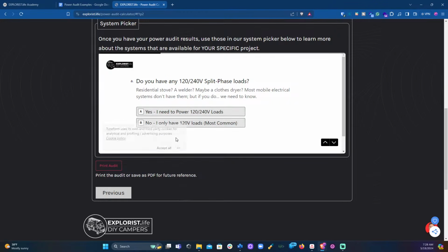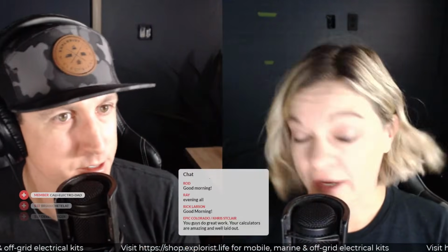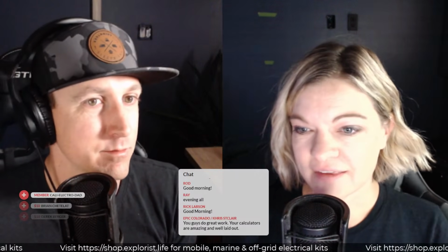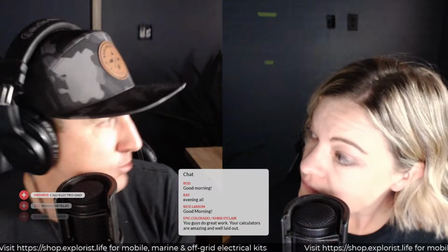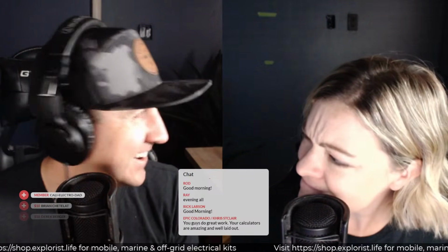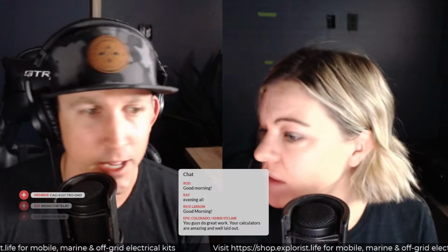Do we have any 120, 240 volt split phase loads? No, we do not. Those are going to be huge loads. Typically that's for residential, like dryers, stoves, welders, big air conditioners. You can have some split phase mini splits. Air conditioners, there are some that are 120, but then there are some that are 240.